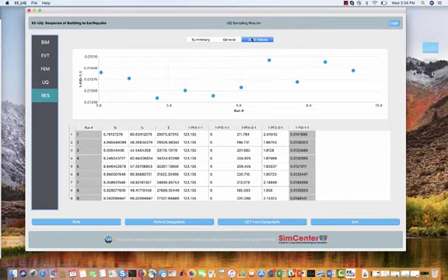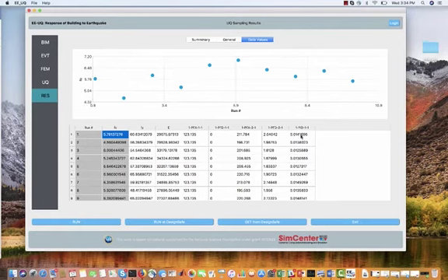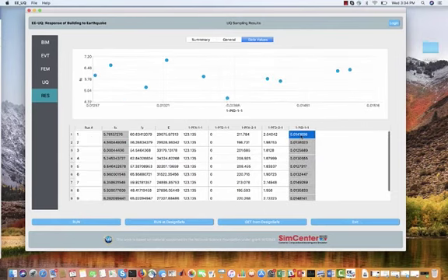When the UQ engine does the forward propagation of uncertainty, it's basically running a number of deterministic samples. And for each sample, it's setting a value to use for each random variable. It does the simulation and calculates the response. What's actually presented is the mean and standard deviation of those values. But we can see how they vary graphically. If you right-click on one column and left-click on another, you start changing the axis. You can see how things vary, FC versus the interstory drift.